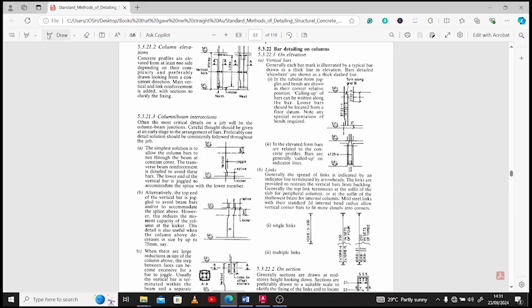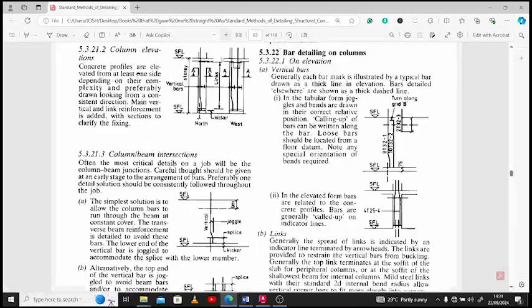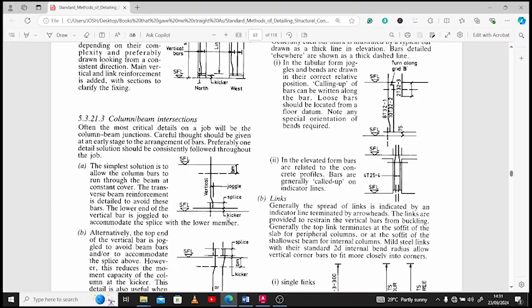The splice bar is what you can see just down here after the kicker. The kicker comes before we can cast the full length of the column on a new floor. So we have a kicker, and after the kicker, the splice connects from the lower floor onto the next floor, then it transmits the stresses into the next one. You see what we're talking about? So let's get to work with this knowledge that we have now.